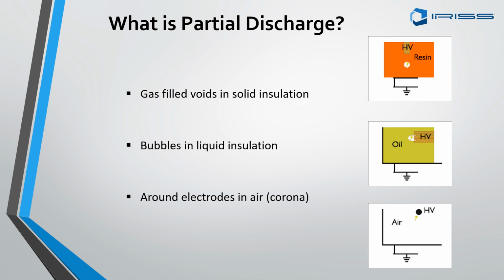And then lastly, you can have partial discharge that occurs in air. Now it's usually a discharge essentially from phase to phase, or again phase to ground, and it's happening partially because air is not a perfect insulating material. Air is a pretty good insulating material, but it's not perfect. So you can have partial discharges that occur just in air.